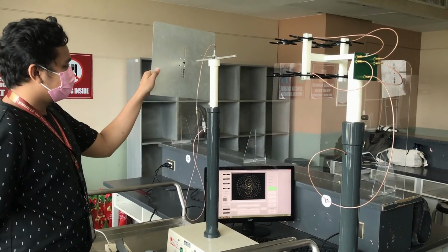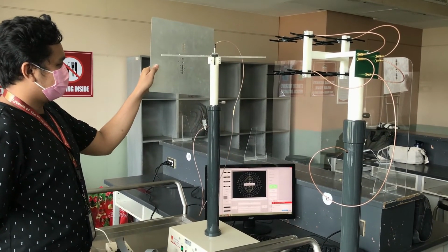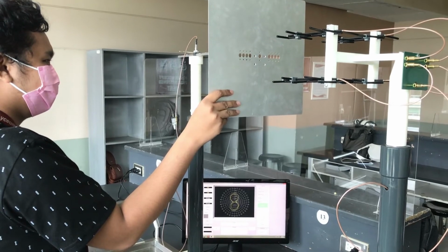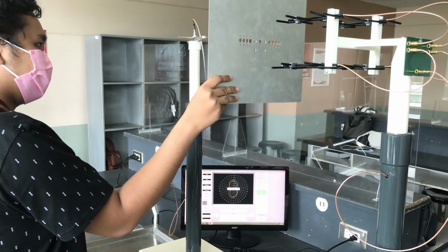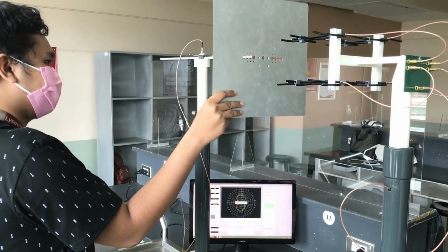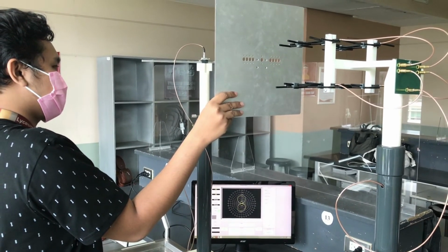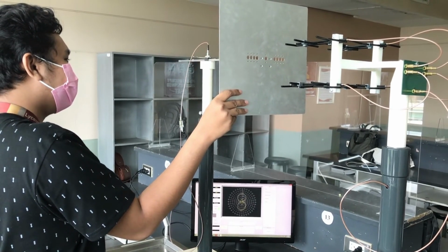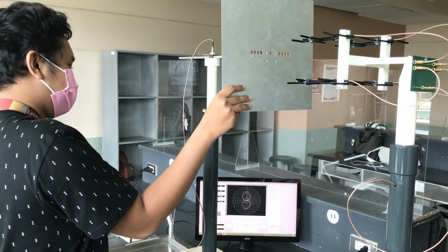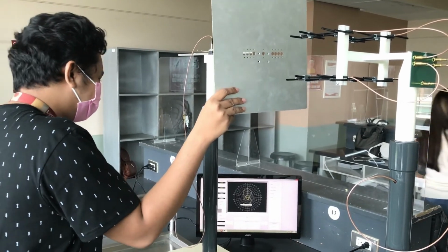For this laboratory exercise, the effects of obstructions to the received signal level was explored. The particular obstruction used in the experiment was a large metal sheet, positioned at various locations around the antenna. In addition, measurements were taken without any obstruction. These measurements served as a baseline comparison for the performance of the dipole antenna with a metal sheet.